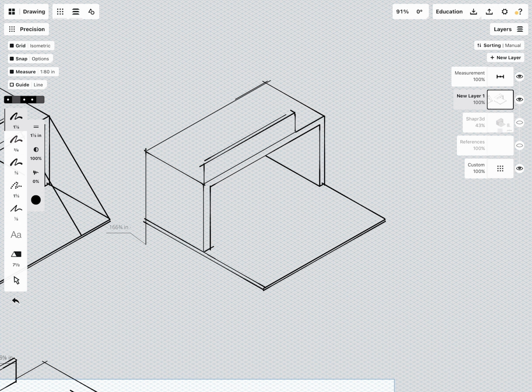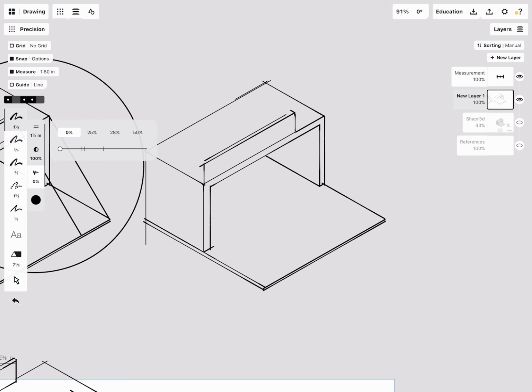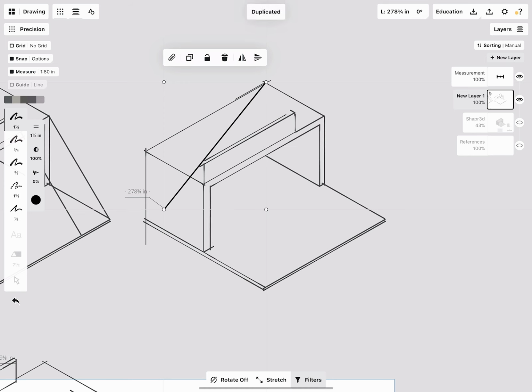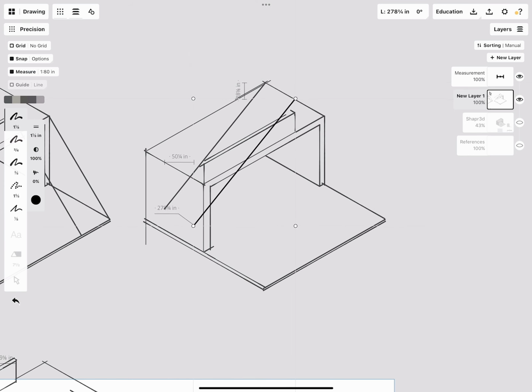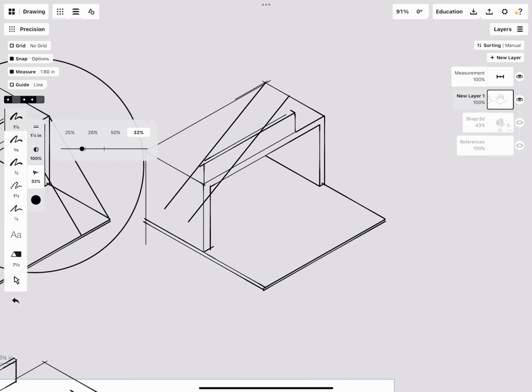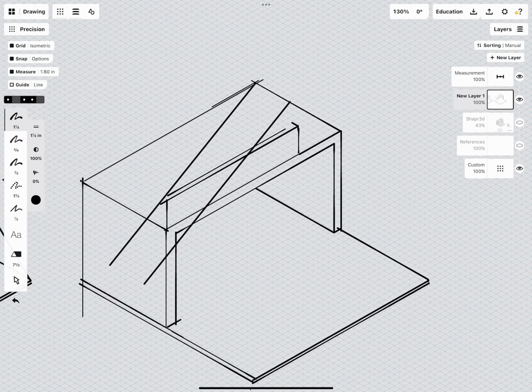And I will now undo this again. Let's say till there. So that is going to be my ramp. So I make a copy, or move this to there, then make a copy, move this to there. Okay, now there I can see actually the ramp, turn the grid back on.